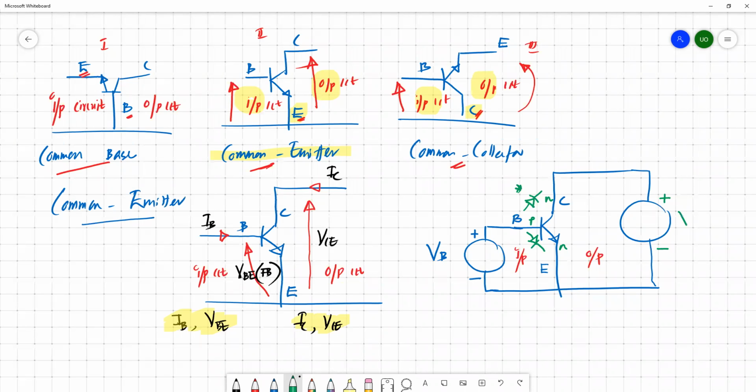So I will assume this is the way we can connect the voltage source, plus and minus. Here we have the negative terminal of the diode, which is connected to the positive terminal of the source. Then we need to verify that this base collector junction is reverse biased due to this applied voltage of VC. So how do you verify whether it's reverse or not? We'll mark the voltage drop. This is your voltage drop VD across B and C.